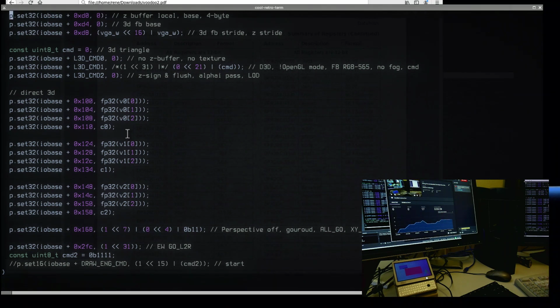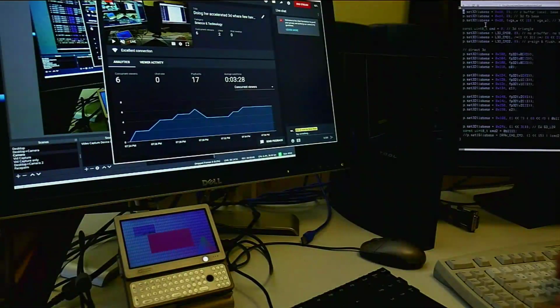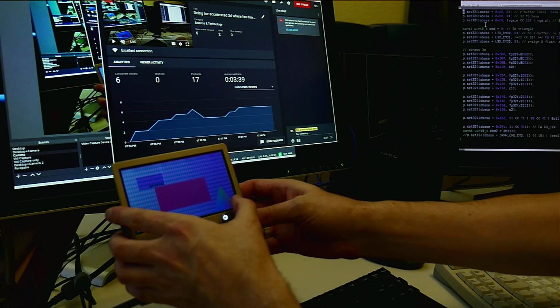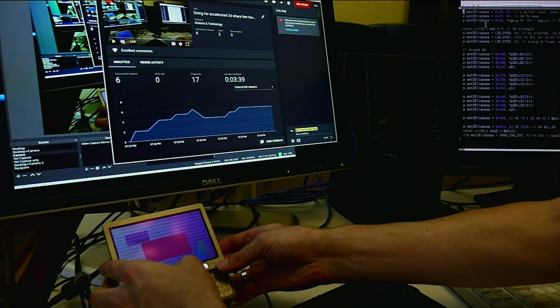Yeah, so just as on the Verge and Voodoo, just filling the registers, the Silicon Motion has something similar to the Voodoo 2 setup engine. On the Verge and the Voodoo 1, you need to compute all the delta values for the edge walker. Edge walker meaning you have the hardware algorithm just walking along the edges and filling this span there.